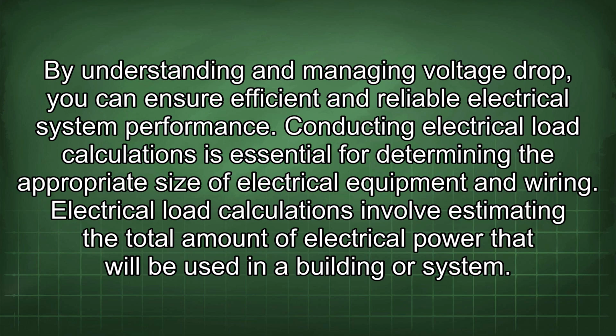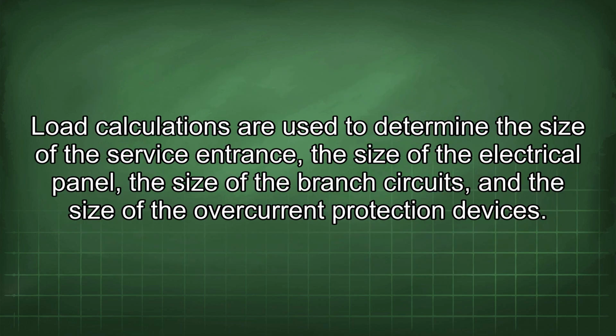Conducting electrical load calculations is essential for determining the appropriate size of electrical equipment and wiring. The electrical load calculations involve estimating the total amount of electrical power that will be used in a building or system. Load calculations are used to determine the size of the service entrance, the size of the electrical panel, the size of the branch circuits, and the size of the overcurrent protection devices.